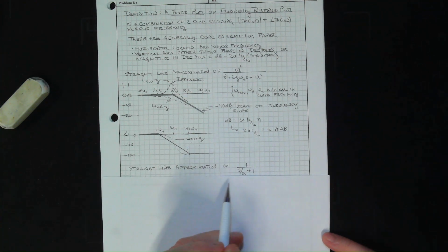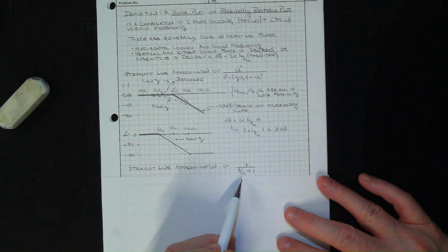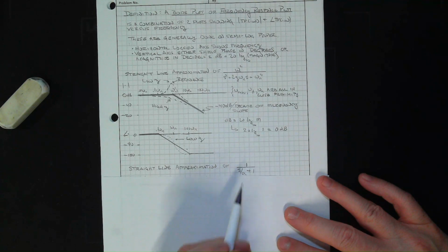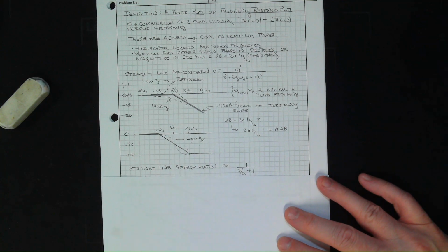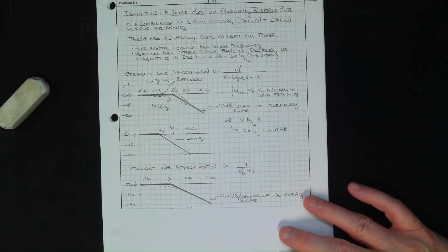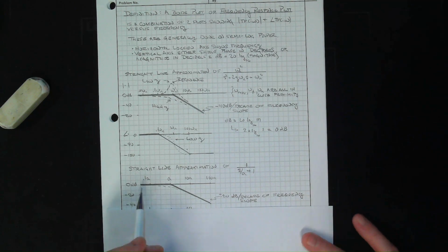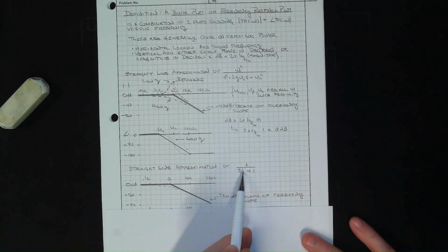All right. So given that, what's the straight line approximation for a first order system? Okay. And here you notice I put it in a unity static gain form. Let s equal 0, I got a 1. So the straight line approximation is basically the same thing. We have 1 power of s, meaning we're going to fall by a factor of 10 as we increase the frequency by a factor of 10, or 20 dB. Okay, those are the shifts we get in gain. And so the approximation says go to A.